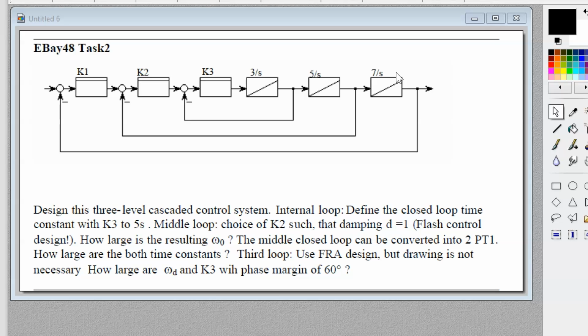There is no frequency omega where the phase is more positive than -180. That means you cannot find any position where you have a positive phase margin. So with a single loop system, this three integrator system cannot be stabilized. But you see, very simple, with three P controllers, not PI, not PID, just simple P controllers with two additional internal negative feedbacks, you can solve this system.